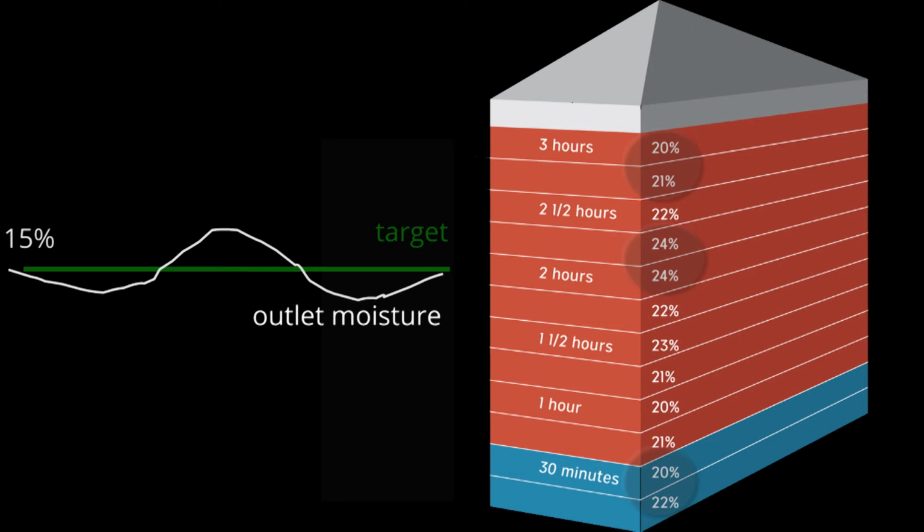It's just not possible. Now, if you run at one rate, maybe the 21% moisture grain will come out at 15%. But the 24% will probably come out at maybe 16.5%. What the DM510 will do is to slow down the discharge rate as the wetter grain gets into the middle of the hot zone.